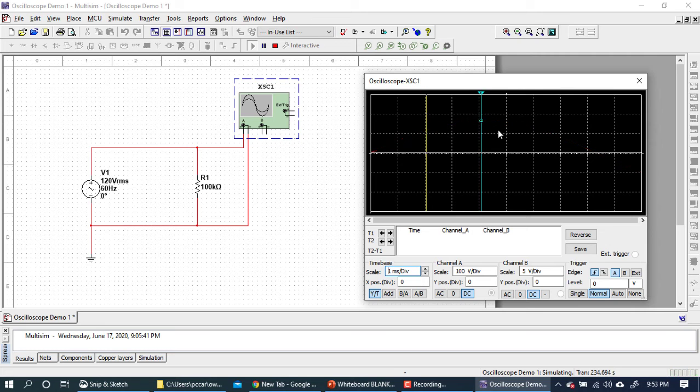And I hope I'm not confusing you. And if I am, you can rewind and go over it to get a little bit of grasp on this. So what I'm having to do here is find half of 4.16666. So I divide that by 2. That gives me basically 2.1. We're just going to round it off to 2.1 milliseconds. So at 1 millisecond per division, I go over 2 divisions, just a little bit more. And that's where I've put the cursor.